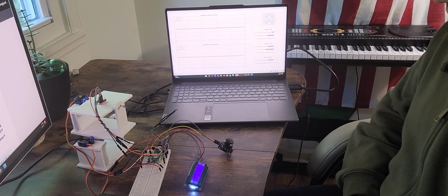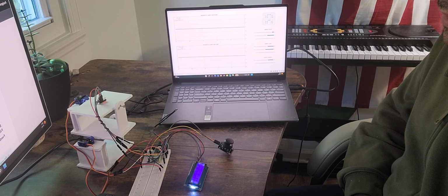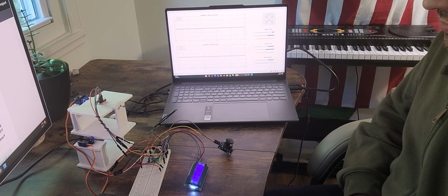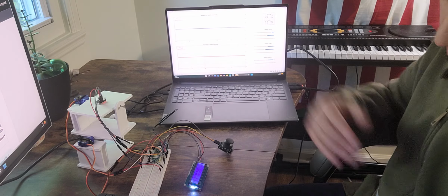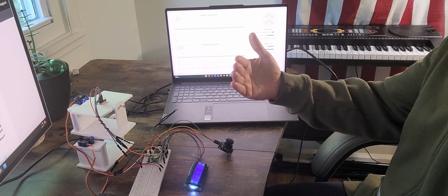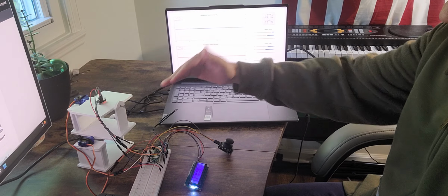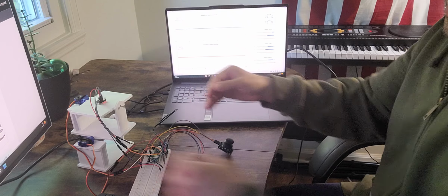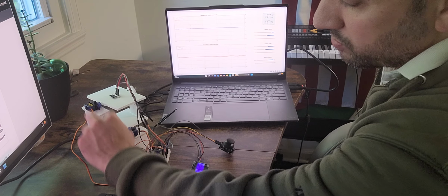Yes, and then for feedback control, I'm using incremental PID. The reason I'm using incremental, not the regular one, is because the error of this platform is not only a function of the position of the IMU sensor, but also a function of the angle of the base of those motors.